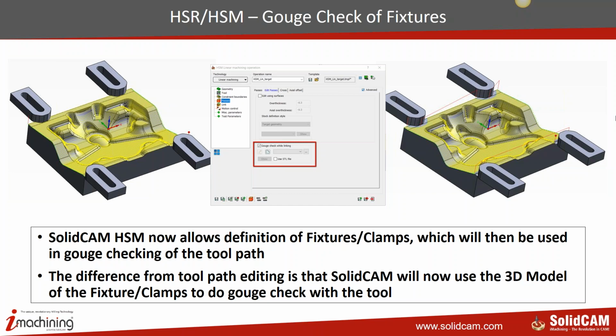Shimshon asked if there are any rules for the linking to the edited toolpath. Well, actually, there are no rules. You can keep the linking as it is. Generally, you don't change the links, but we allow you to change the links while the editing is happening. So if you have created a toolpath, you could change it to bidirectional, or you could change it to conventional when you're creating the edited toolpath. But generally, it's not suggested to touch your links when you're doing editing. You would like to keep the same linking that is there in your original toolpath.